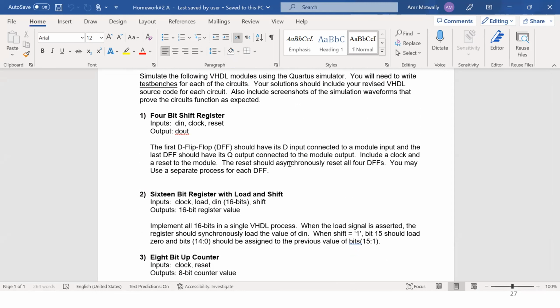We spoke about shift registers last week, and we saw how the data will be manipulated. If you need a reminder, you can go to the same lecture and see it. To implement this one, you can program it to move, but there is a function in VHDL you can use to make this shift register.